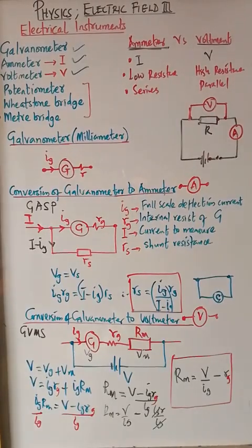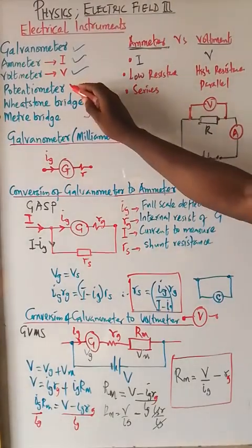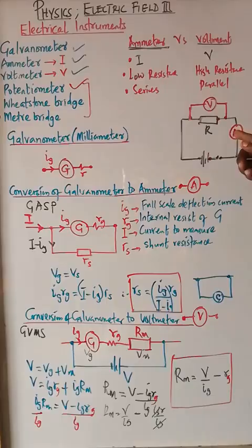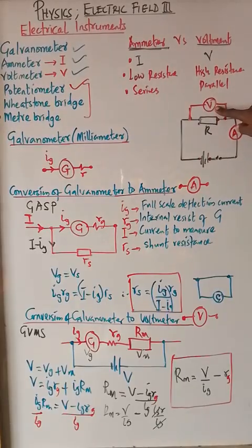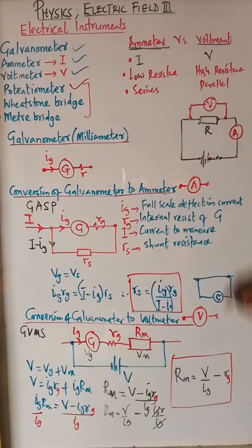Now the next, let's move to potentiometer. We have a small problem here because voltmeters also have their own internal resistance. No matter what, they have internal resistance, and they are also going to draw current from the circuit. So most times when we use a voltmeter directly, our answer is not usually accurate. So there will be some loss in what? In PD. So in order to deal with this error, we have the potentiometer.